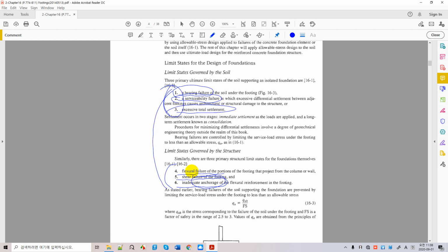anchorages should be adequate. The anchorages, lap details and development lengths from a column to the footing or from the footing to the columns must be strictly designed well so that they do not misbehave while taking vertical load.